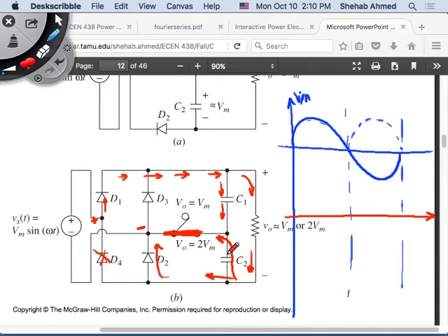Well, capacitor is an impedance, right? Transient, because I'm talking about transients, right? Capacitor in steady state is an open circuit, right? Or capacitor to DC is an open circuit. Here I don't have an AC high frequency current. I sort of have a low frequency current, so it will have a large impedance. This capacitor is a large impedance.